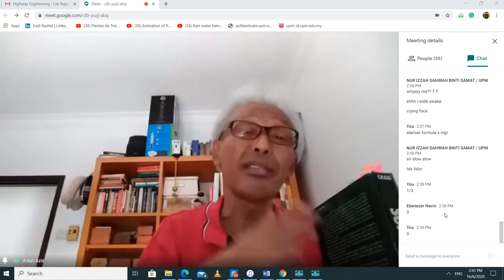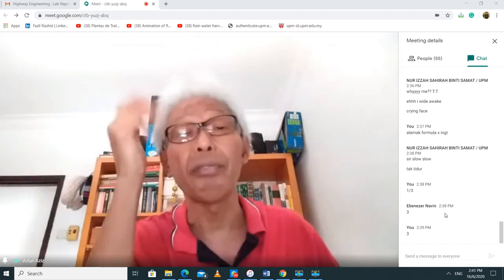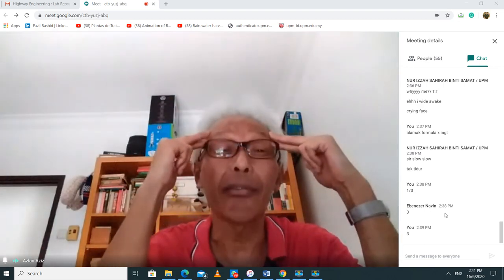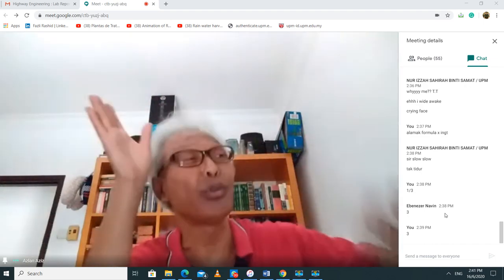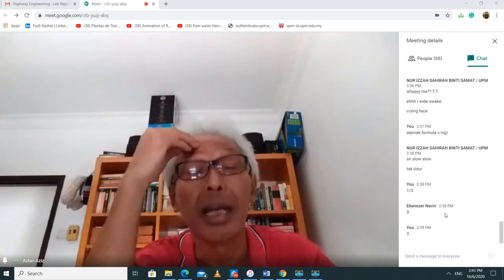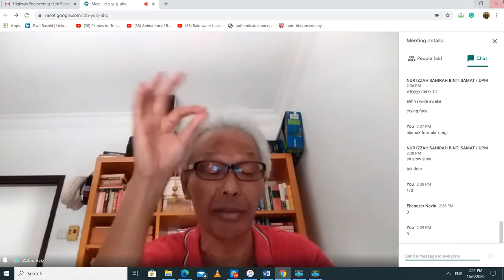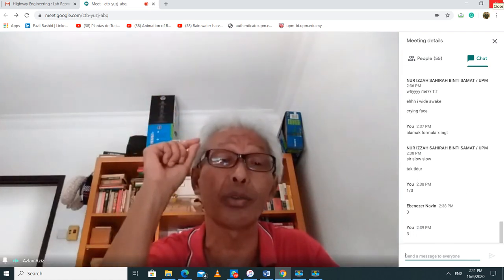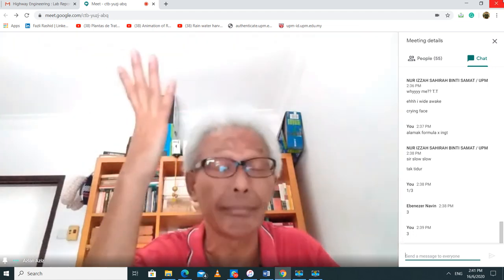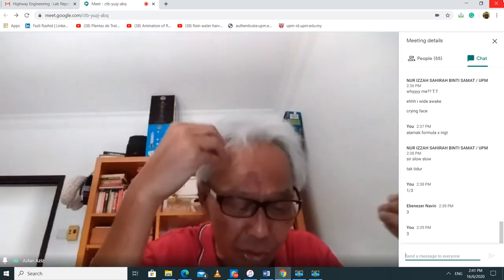Now, in between these two types of failing, you have K0. K0 is the coefficient at rest. In other words, you don't do anything to it. At rest means you have your element, it's just sitting out there nicely. That is why you have this ratio sigma H over sigma V equal to K0. You will see later it's always a constant value. It's not a function of phi. So I'm just trying to put all this into your head.